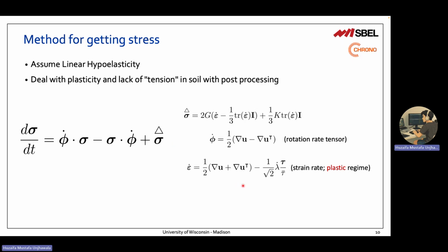Obviously sand is not completely elastic, right? It can flow, as I said. So that is plastic deformation and plastic flow. We ignore that at first. We just take the total strain, which includes an elastic part and a plastic part. The plastic part is what I removed right now. So for now, we ignore it, but we come back to that a bit. So once you have this elastic part, you can use this linear hyperelastic elasticity assumption and get your stress rate, and you can integrate that to get your stress.